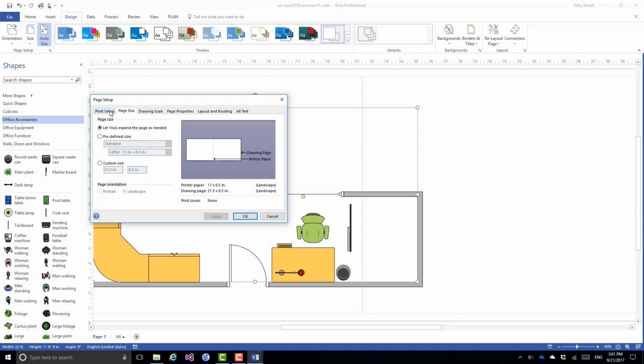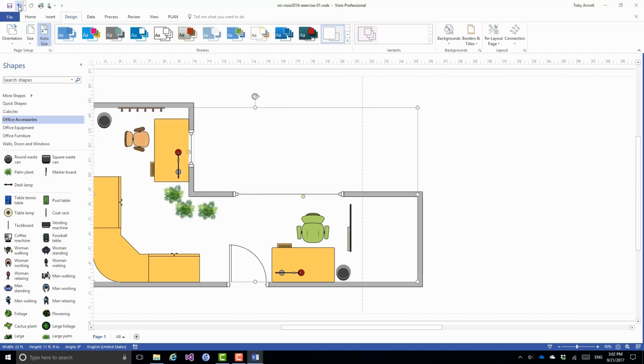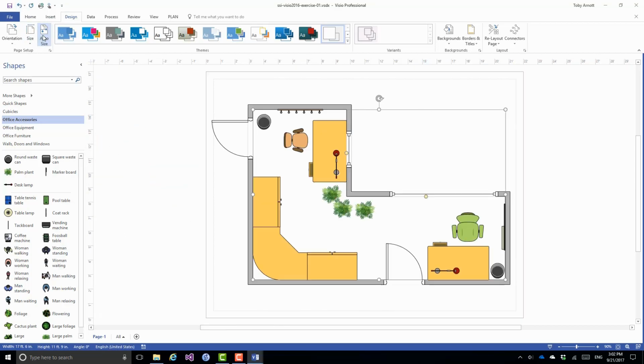And if I go to Print Setup, the little graphic there will tell me the same. Now, of course, I could use the print zoom facility to scale it down to fit onto a page still, but of course it's going to make all the detail much smaller. So now you can see the difference between the page size, which is sort of 2 pages if you like, or at least it's more than one, and that would need 2 sheets of letter size paper unless I did some print zooming. Now let me cancel that and undo that and switch off auto size.